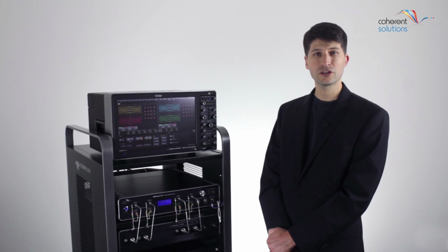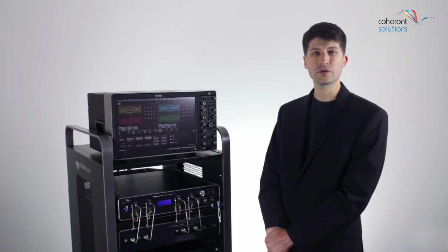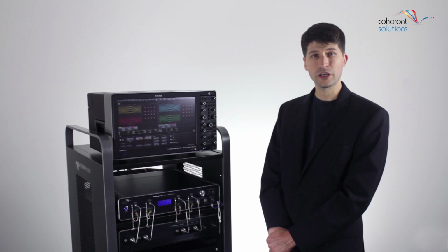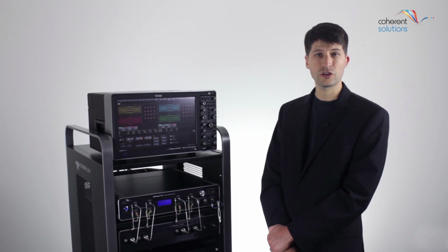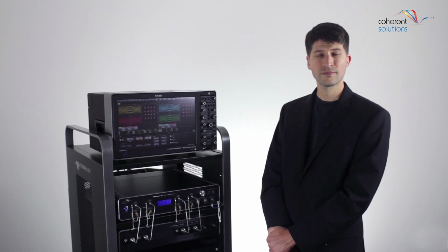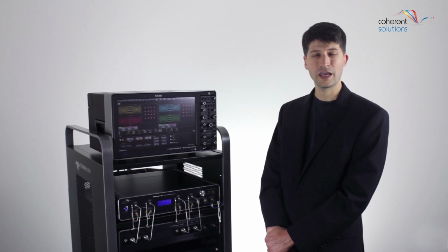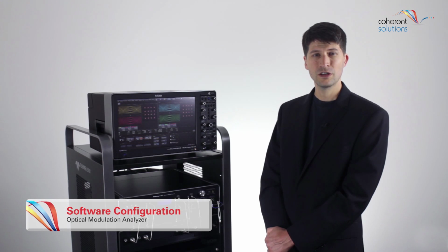A second application is to mimic commercial coherent receivers. In this application, you may want to decrease the receiver bandwidth, use match filter designs to match the filter in the transmitter, use DSP algorithms with equalizers to increase the eye opening and give you the best bit error rate performance possible. Both of these applications are possible with the Optical Link and OMA system. So let's explore the OMA in more detail.